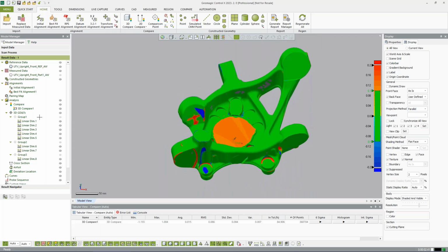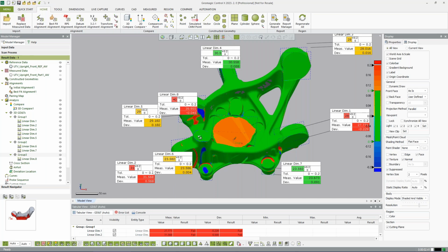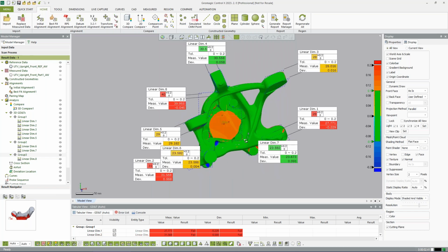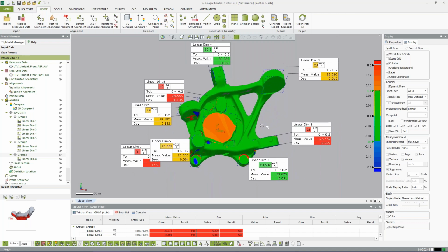So usually, once you have your color map set up, throw your part in, throw your dimensions in, we're only going to have to do this once. And then, I overrode some of these dimensions. I think I went the right way, but we're showing some things are a little undercut of what we want if we wanted to do like -0 because we only want them minimum thickness. So we're showing a little low on some of that stuff. Some of the things were a little undercut based on our tolerance of 0 negative. So we highlight and flag those things right away. And we could do a bidirectional color map too, like if we wanted to show anything that was grossly low or something like that, we could set that up.